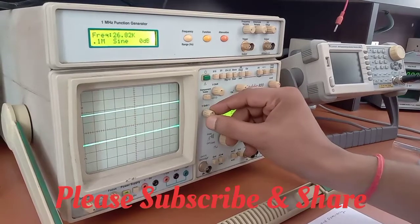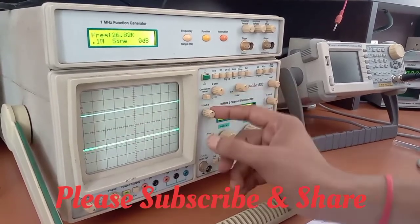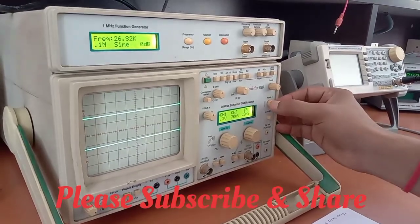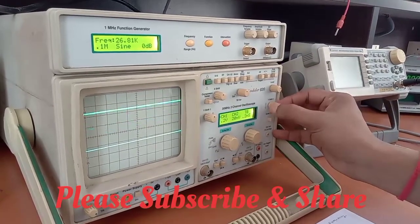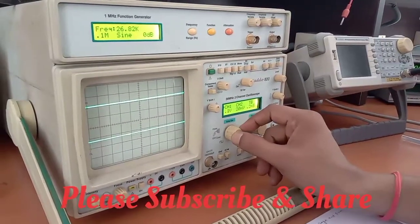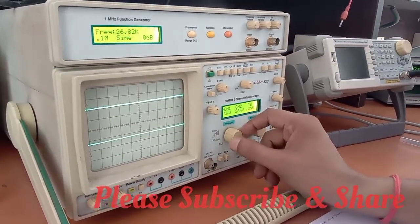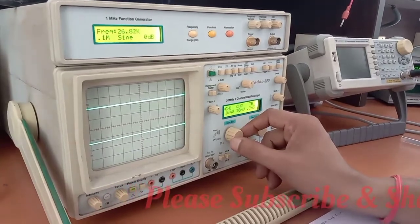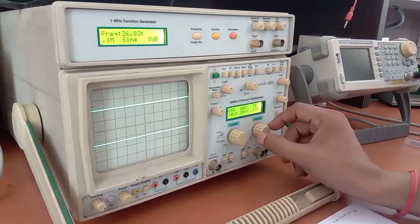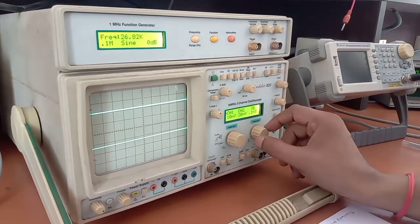This is Y shift, the Y shift of channel number 1. So we can change the signal waveform in the vertical direction for channel number 1, and through this shift we can change the vertical direction of channel number 2. This is volts per division, and this is time per division. From this voltage per division we can change the voltage per division of the input signal, and from this time per division we can change the internal time generator. We'll see shortly how to change it and how to measure it.